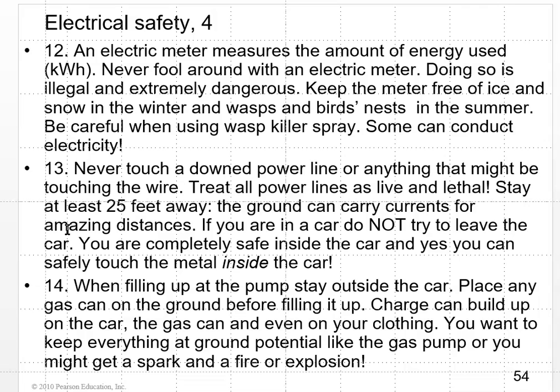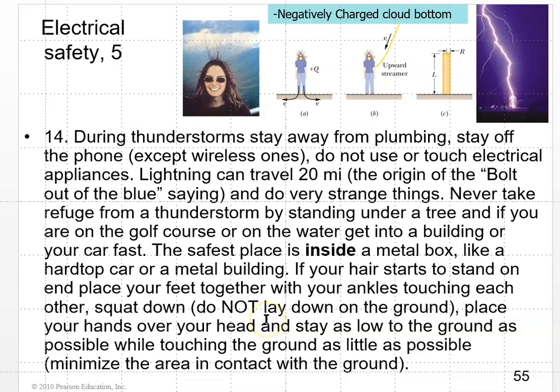When filling up at the pump, stay outside the car. Place any gas can on the ground before you fill it up. Charge can build up on the car, the gas can, and even on your clothing. You want to keep everything at ground potential, like the gas pump, or you might get a spark and a fire or explosion. During thunderstorms, stay away from plumbing, and stay off the phone except wireless ones.